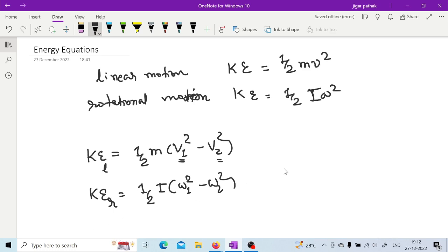Sometimes potential energy may also be the energy absorbed by the brake, in the case of hoists and so on. We are absorbing the potential energy, which is given by mgh. Whatever energy we are transferring through the brake is ultimately converted into heat energy.